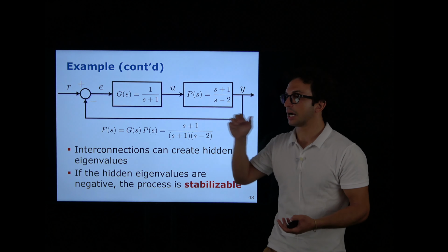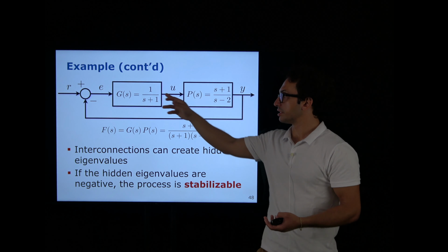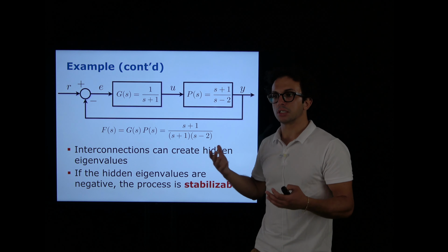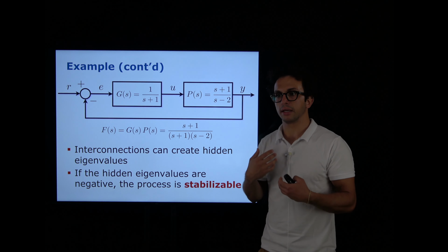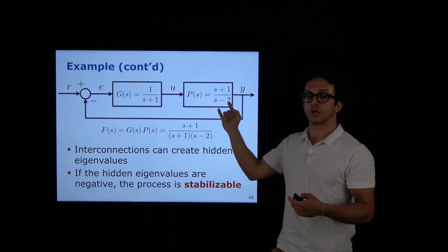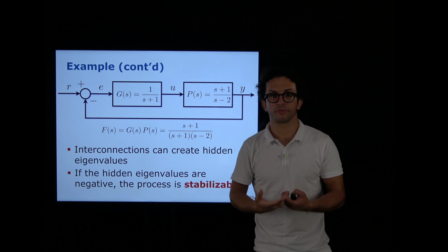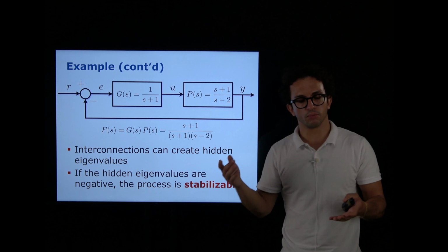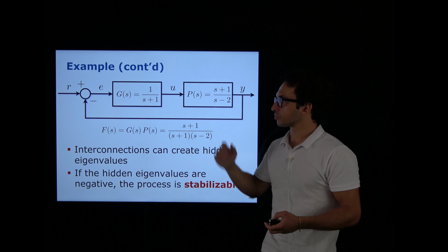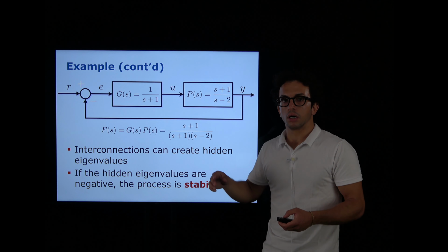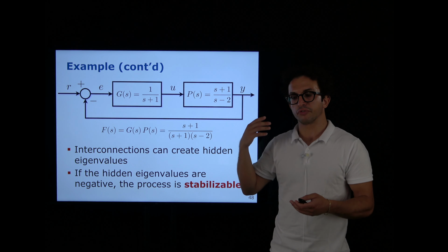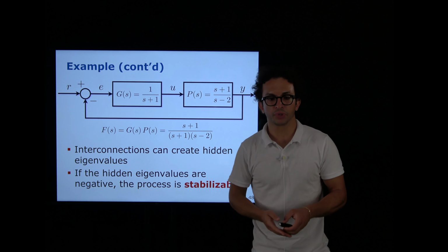On the other hand, if we had a zero here, which would simplify zero to pole, in that case it would be uncontrollable, because it's not something that the controller can deal with by changing its poles, since it's an eigenvalue that belongs to the system itself. So this is just an intuition to more or less understand how uncontrollable and unobservable poles appear. It's not strictly part of the course, but it was just to give you some understanding of how they are created.